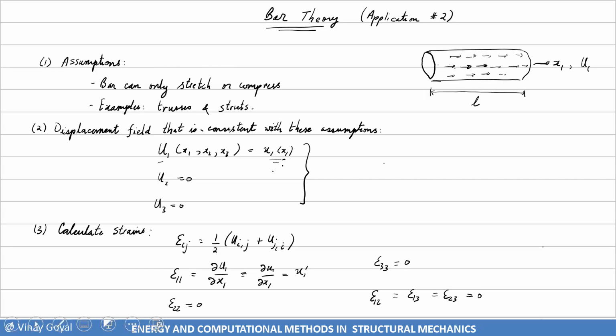And I applied tractions here as an example, like on the lateral surface, but there's many other ways you could apply that traction. There's not only one way to do it, there's many other ways to do it. So if I apply the principle of virtual work, it states the internal virtual work equals the external virtual work.